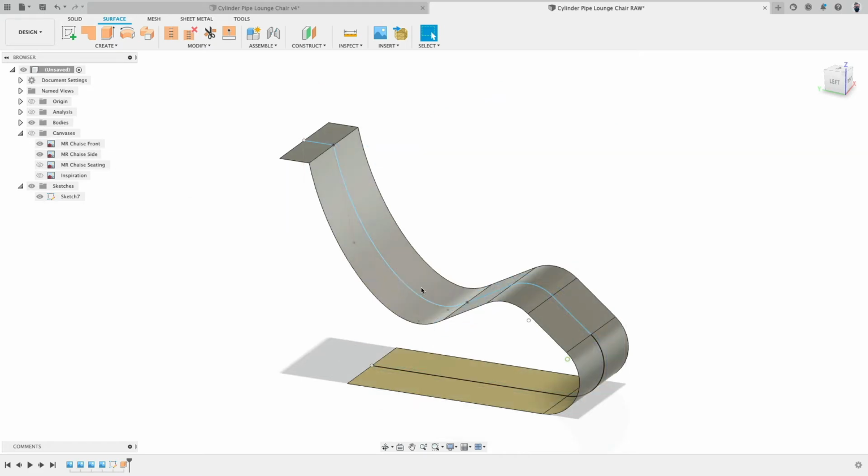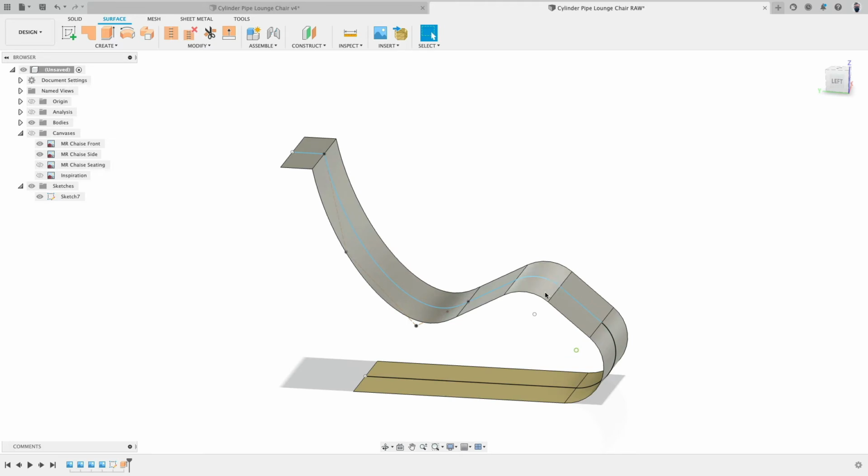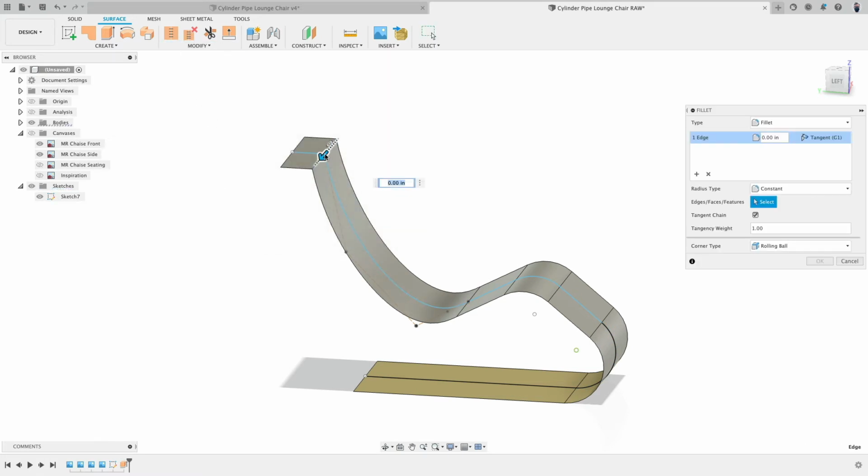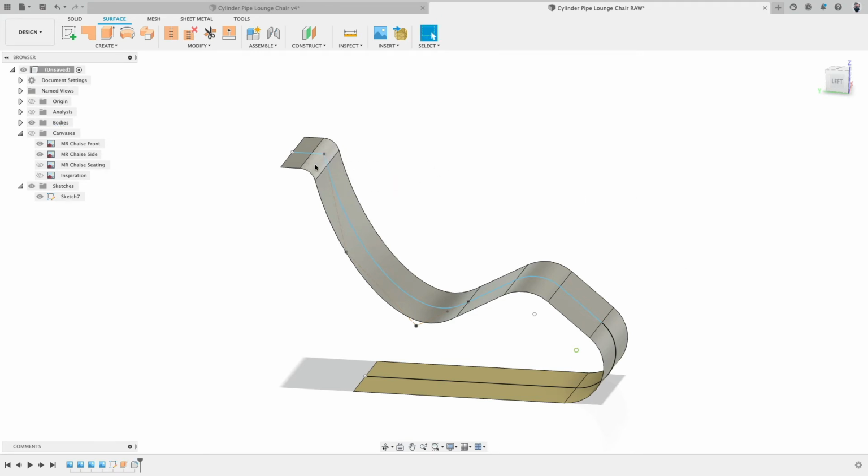I did actually not fillet this corner here in the sketch on purpose, just to show you there are two ways in general how you can do this. Inside the sketch, I rounded these lines. Or if you want, you do not fillet the sketches, and then in modeling, like what I'm doing right now, we add a fillet. The outcome for the surface is pretty much the same.